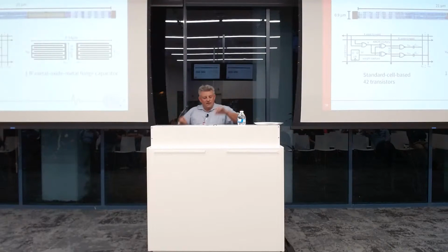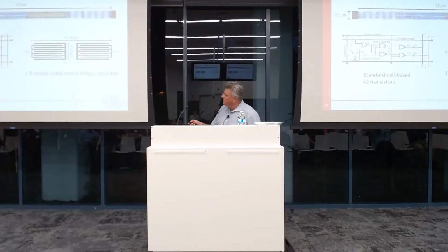Each unit looks like this. This is a differential circuit in the end, so it's not one cap per cell, it's two caps. Then we have this multiplier, and this is the local latch that creates the weight stationarity. You see this is a fraction of a micron, 20 microns wide. Then we stack 1,000 of these in this direction, and 64 of them in that direction, and call it a chip. That's basically what's going on here.